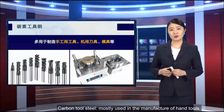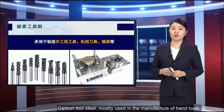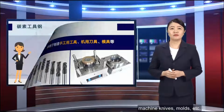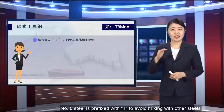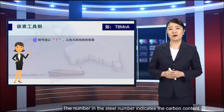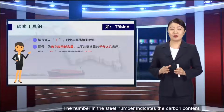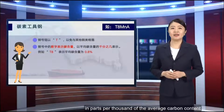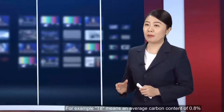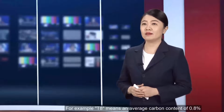Carbon tool steel. Mostly used in the manufacture of hand tools, machine knives, molds, etc. Number 8 steel is prefixed with T to avoid mixing with other steels. The number in the steel number indicates the carbon content in parts per thousand of the average carbon content. For example, T8 means an average carbon content of 0.8%.